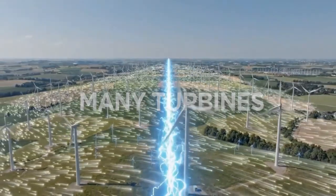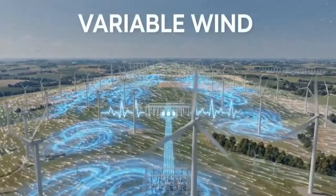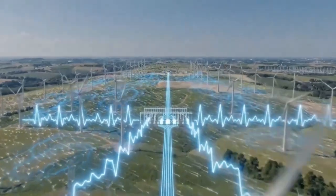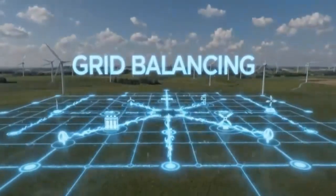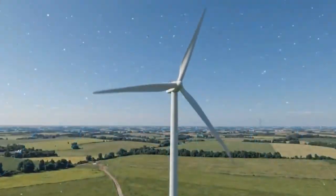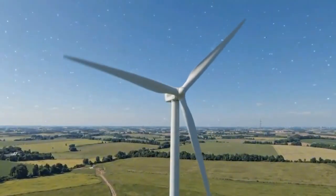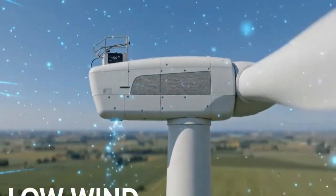At rated wind speed, the turbine produces high power while the control system keeps the rotor within safe limits. If the wind becomes too strong, the turbine reaches cutout speed, feathers the blades, and slows the rotor. So a wind turbine works best within a specific wind speed range, not in every possible condition.